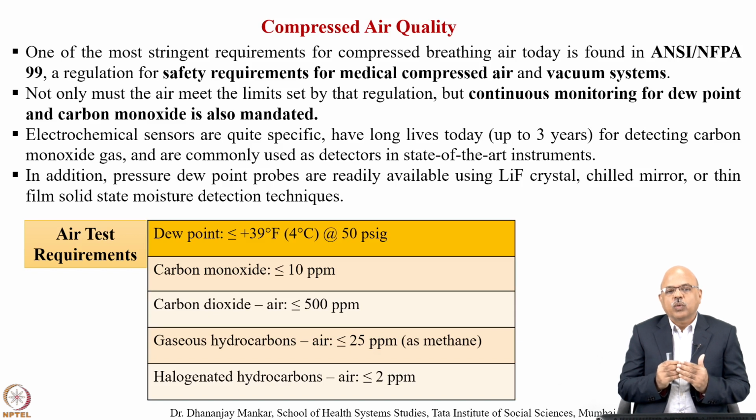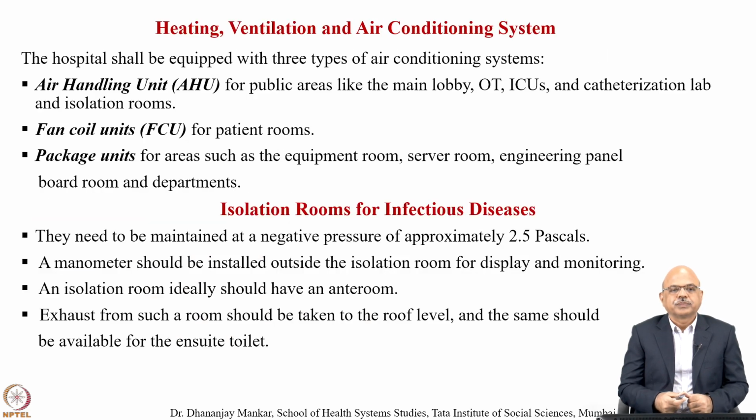Electrochemical sensors are quite specific and have a long life today, up to 3 years, for detecting carbon monoxide gas, and are commonly used as detectors in state of the art instruments. In addition, pressure dew point probes are readily available using lithium chloride crystal, chilled mirror or thin film solid state moisture detection techniques. So the air test requirements are being shown in the figure over here.